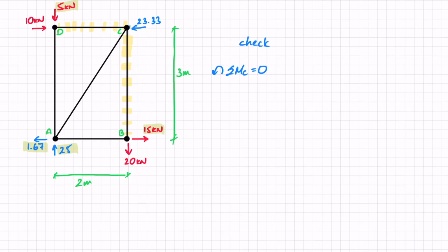So two things you need to find here: direction and distance. The direction of the moment, clockwise, is negative, counterclockwise is positive, and in terms of the distance, it is always the perpendicular distance. So if you have a force in x, you're going to need a distance in y, and if you have a force that is in y, you're going to need a distance in x.